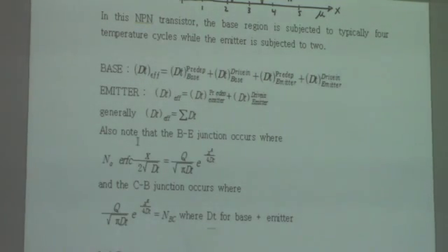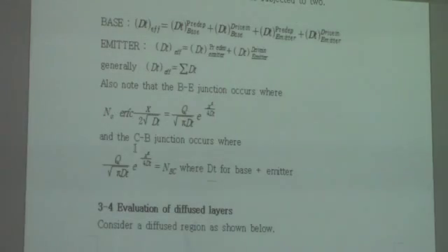And so we use the complementary error functions and the Gaussian profile to determine the profiles of the dopants, and so we set the junction depth where the two different dopant atoms, the concentration of dopant atoms are equal.